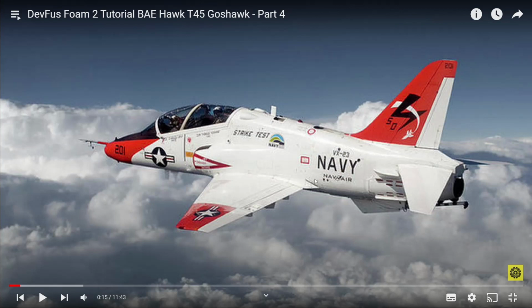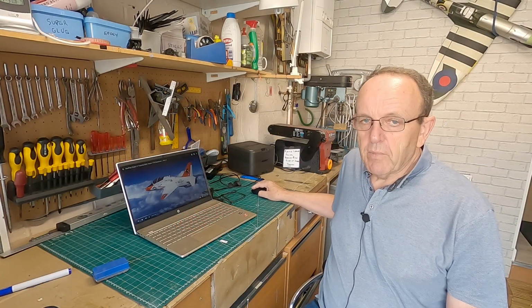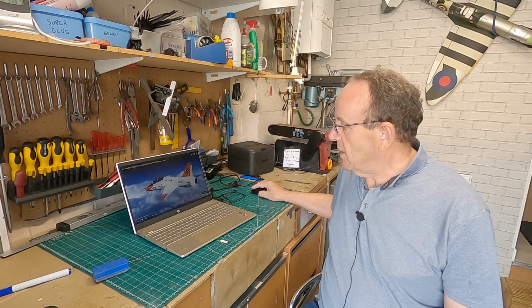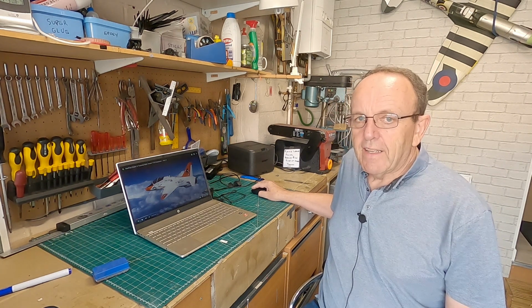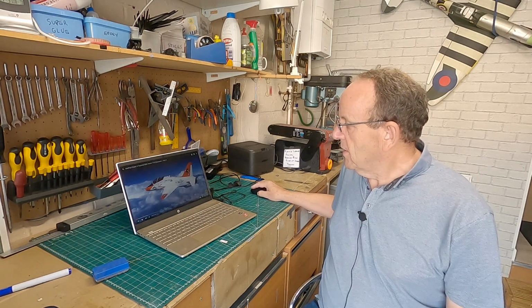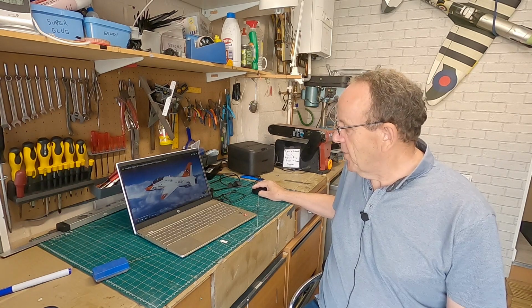The only problem was I didn't get the design right and it hardly flew at all. So that's on my to-do list to make one that's slightly bigger. I know where I went wrong with it. I got the placement of the EDF wrong, and the nozzle wasn't big enough, so it just never had enough puff to get it going.